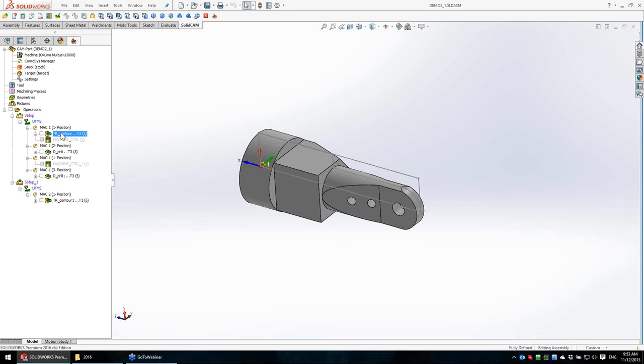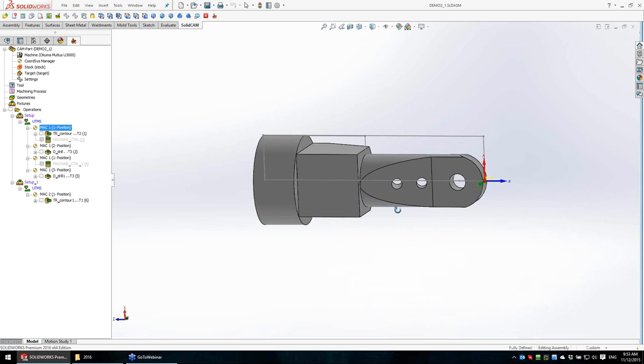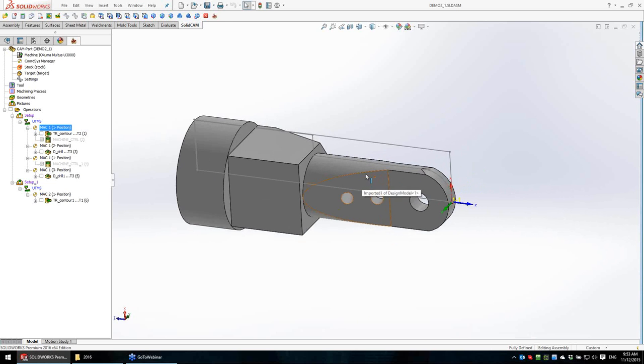For the turning operation, I don't need to do anything. The coordinate system oriented like this is okay. The setup is okay. I don't have to change anything. The MCO I suppress. Now, the second setup, I don't need it. I can transfer the part to the back spindle on this machine and continue to work, so I don't need another setup. Let's delete it.